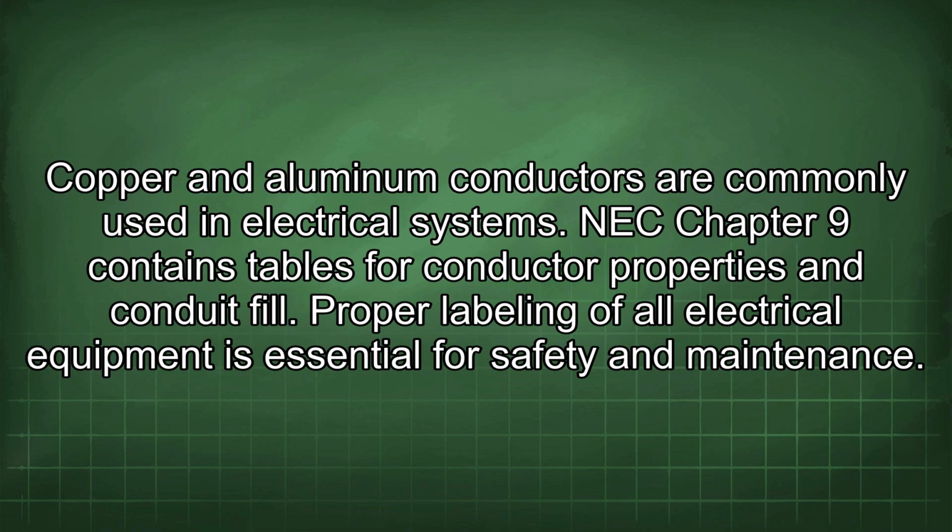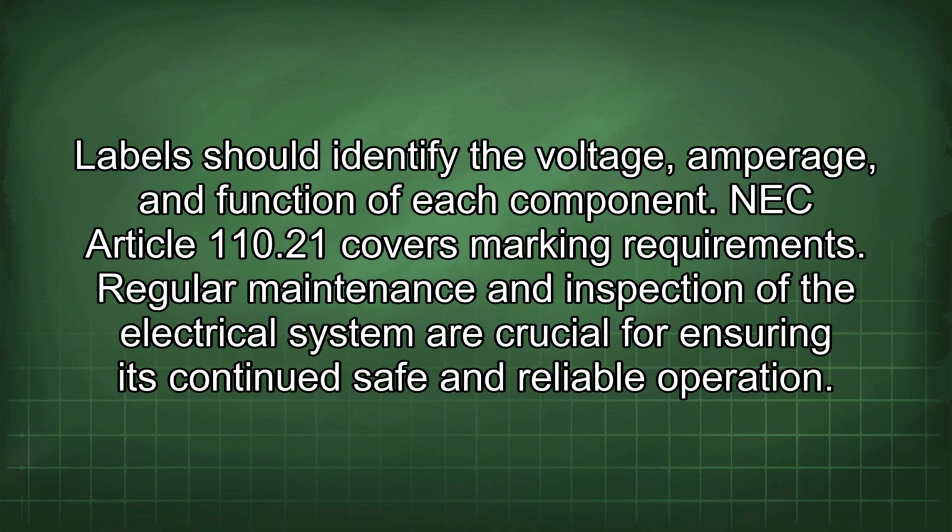Proper labeling of all electrical equipment is essential for safety and maintenance. Labels should identify the voltage, amperage, and function of each component. NEC Article 110.21 covers marking requirements.